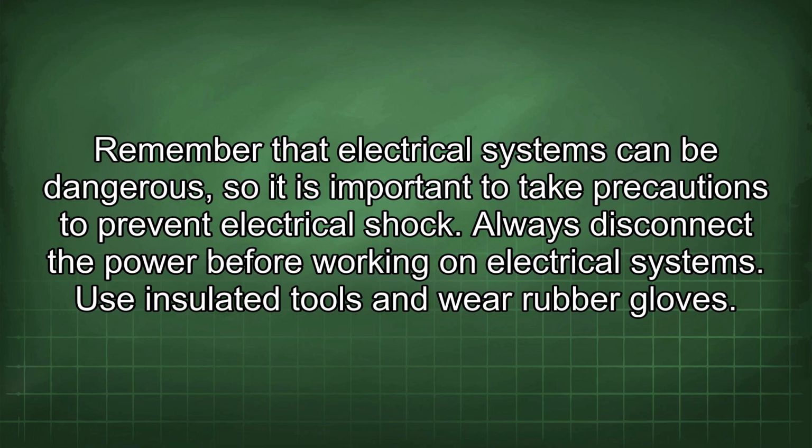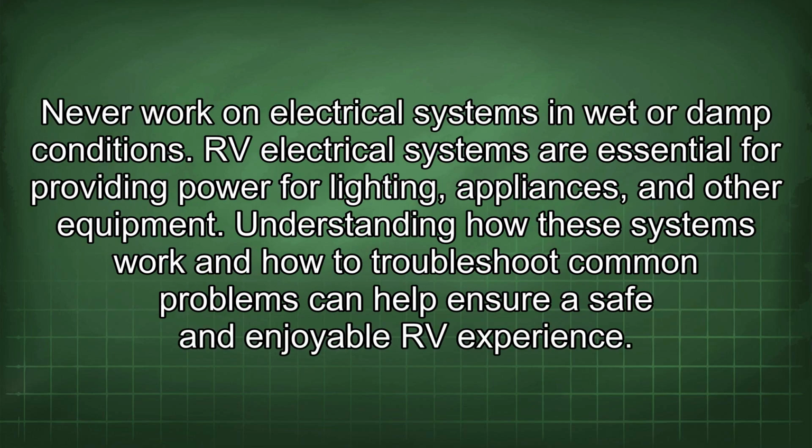Remember that electrical systems can be dangerous, so it is important to take precautions to prevent electrical shock. Always disconnect the power before working on electrical systems. Use insulated tools and wear rubber gloves. Never work on electrical systems in wet or damp conditions.